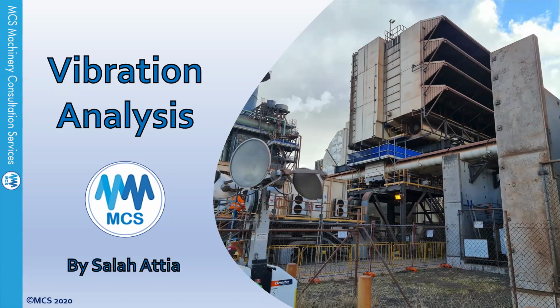We need to see how the pump looks, how the bearing looks. Is the pump centered between the two bearings, or is it overhung? All these things can affect the vibration pattern and the answer.